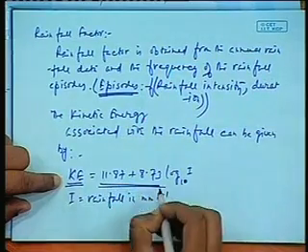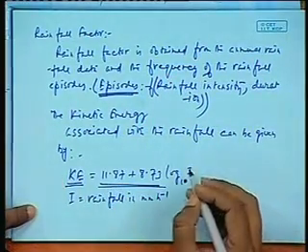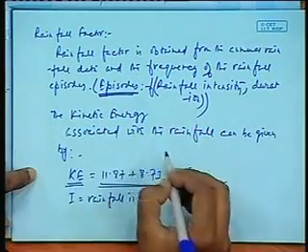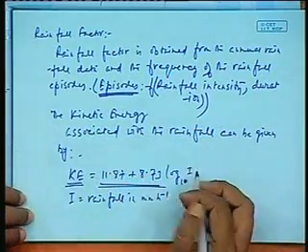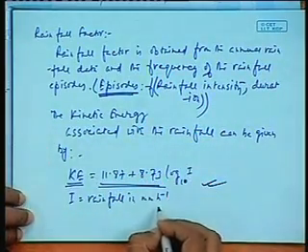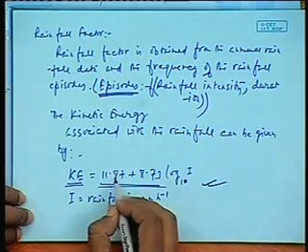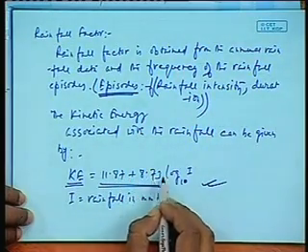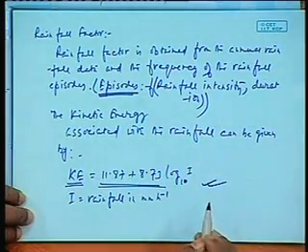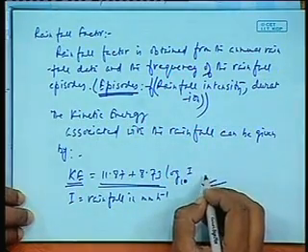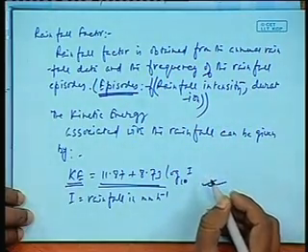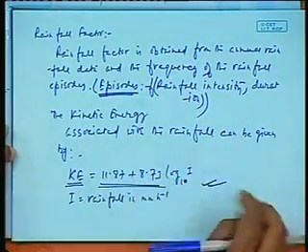So this KE is just for your interest, though we will not use this; it's just for your information. KE equals 11.87 plus 8.73 log10 of rainfall in millimeter per hour, and I think this would be in joules. So kinetic energy can be known like this.